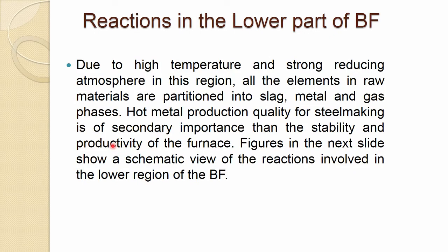because it's sort of like a black box, which is just a covered container, while the steel making operation is a batch type of operation where you can easily manipulate the operation and adjust the chemistry of not only the hot metal but the steel. So, that is why in the blast furnace we try to control chemistry as much as possible, but not in the utmost way. But the utmost importance is the stability and operation of the blast furnace. So, figure in the next slide.